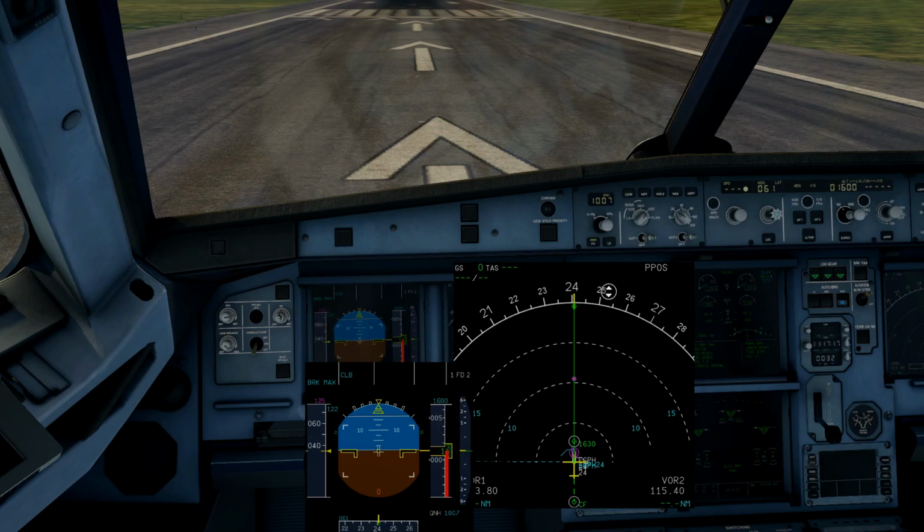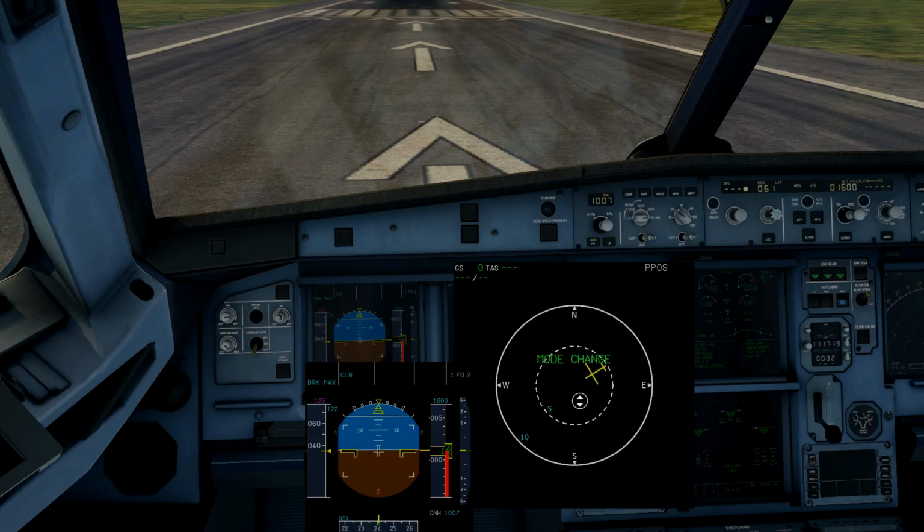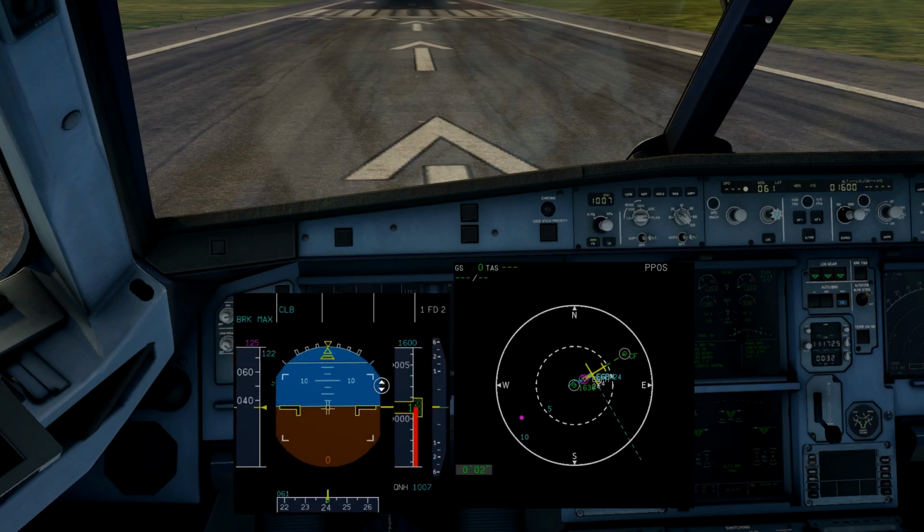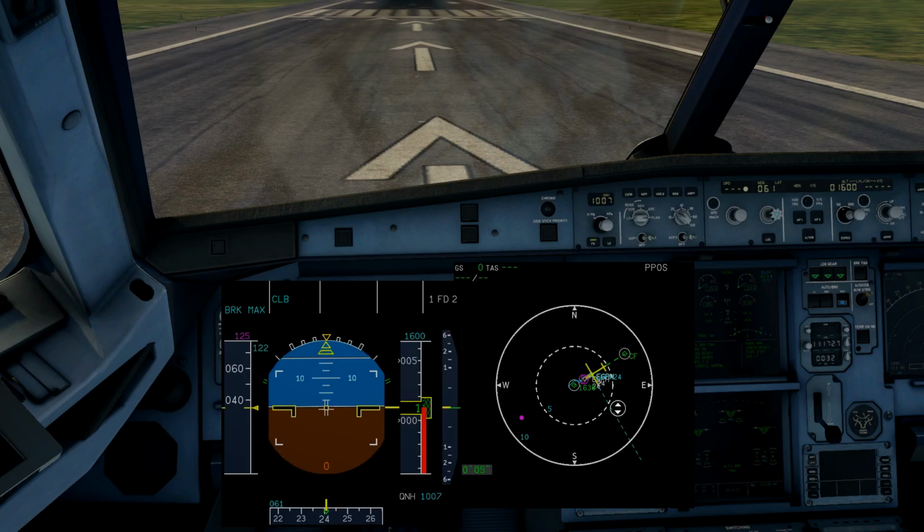As soon as we reach the beam of the threshold, we will start our clock, which is known as the chrono. As soon as it reaches 35 seconds, we will begin a left hand turn towards the runway, and we'll land in Edinburgh, but we will not stop at the runway. We'll take off and we'll go again.